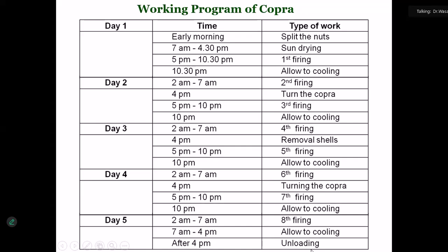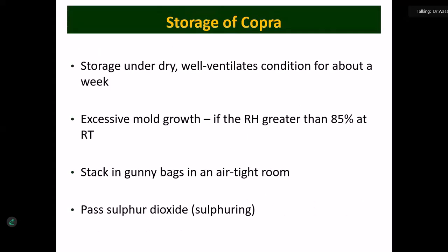What you have to note here is that it is not continuous time. Normally 5-hour firing, 5-hour firing, and 3.5 or 4-hour cooling. 2 times you are turning. On the third day, normally you are removing the shell. That's all. Then modern copra dryers I am not going to discuss here.